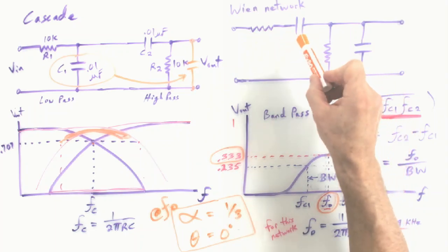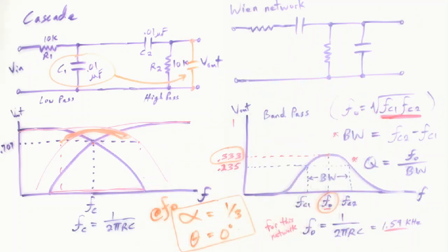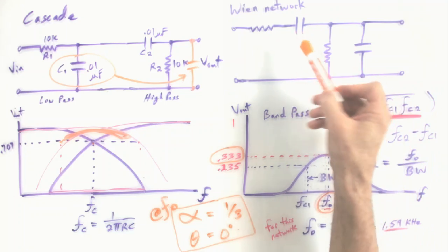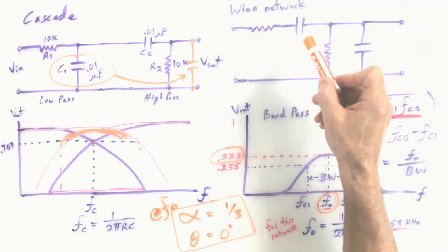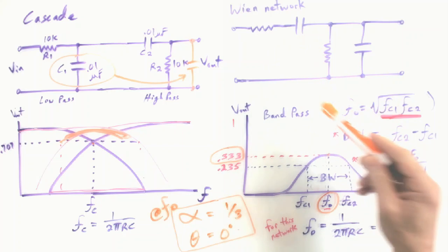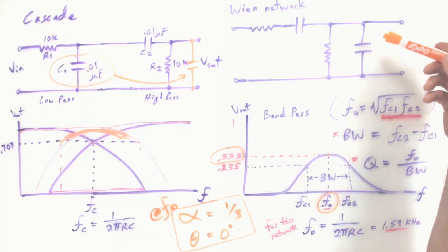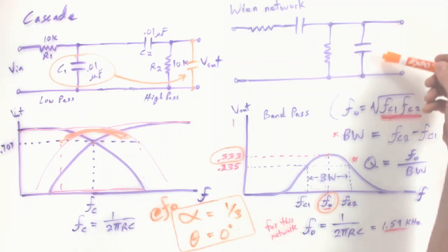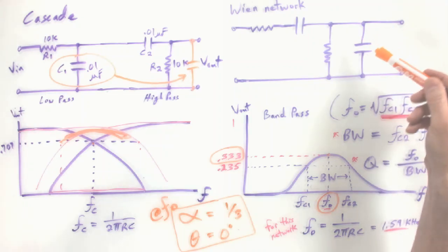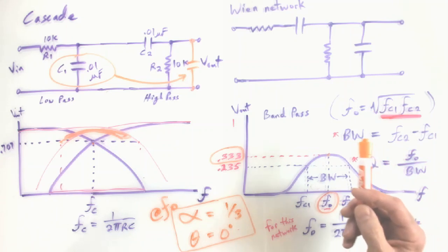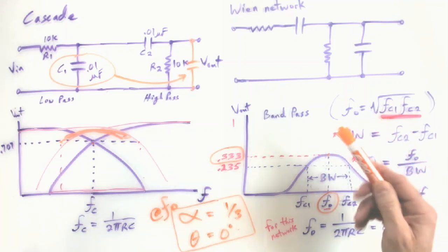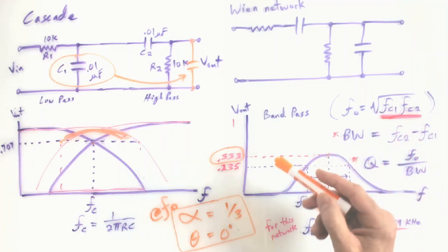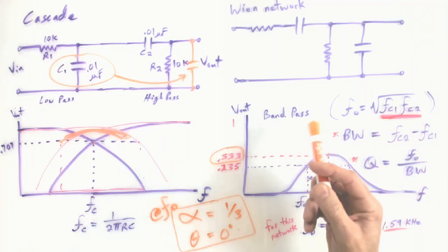So you have your high pass component still, and in fact, it'll be a series design high pass. And here you've got your shunt design that'll shunt high frequencies, so low frequencies will get through. Or maybe another way of looking at that is just pick a low range of the frequency and see what happens.